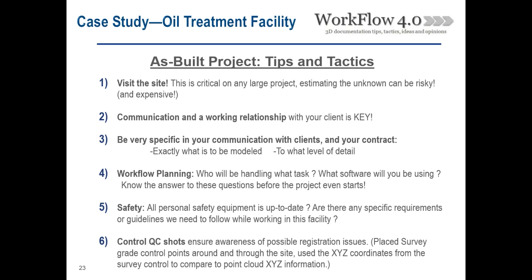Quality QC shots. This is what I was talking about earlier, being a survey company. We use these to ensure awareness of possible registration issues. And as I have placed here, it says place survey control points around and through the site. And we would use the XYZ coordinates from the survey control and compare those to the XYZ information in the point cloud.